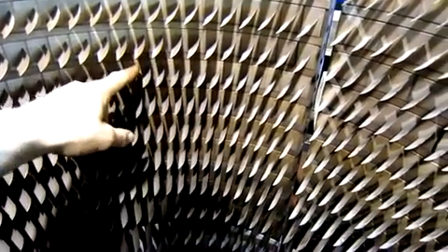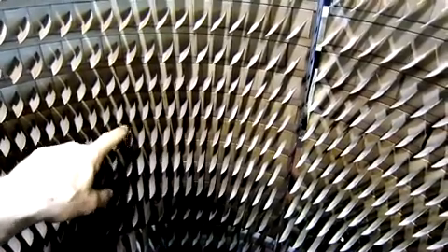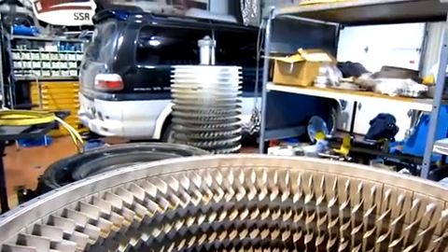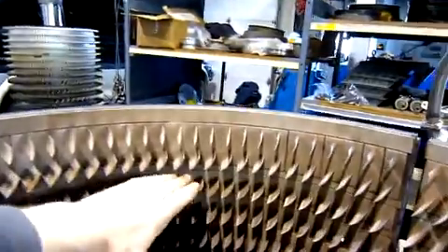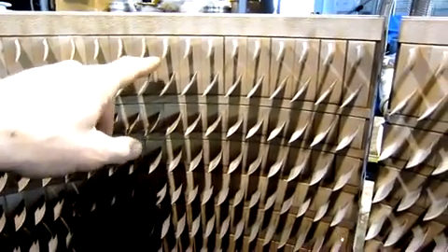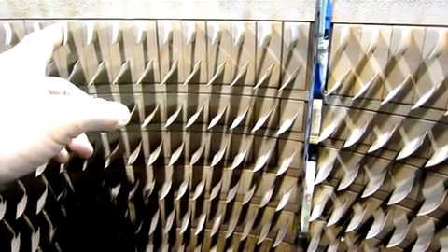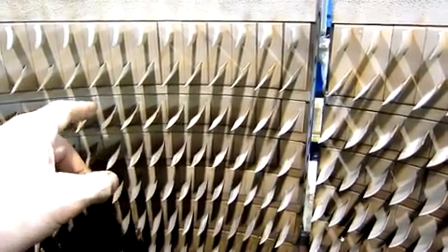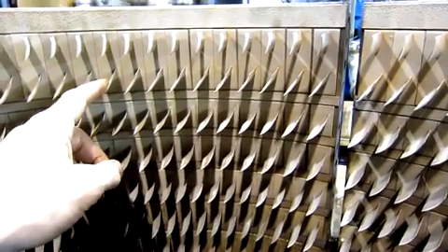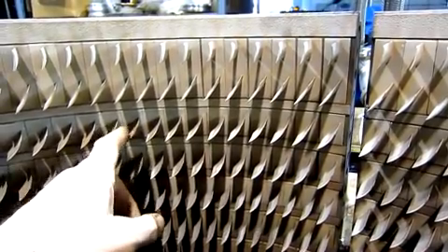The diagrams that we see don't show every stage of stator. There's a stage of stators behind every stage of the compressor rotor. Each of the stages of the compressor rotor matches up with one of these slots, except for this one. Now, we've covered this in a previous video, a couple of years ago actually. These are called the outlet guide vanes. They're a form of compressor stator, but because they're the last thing that the air sees before leaving the compressor, they're called outlet guide vanes. You could call these stator guide vanes, but they're usually called stator vanes.